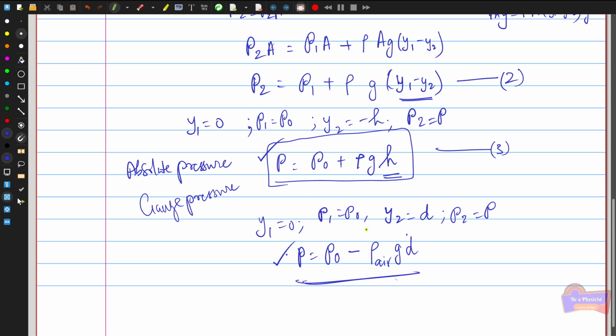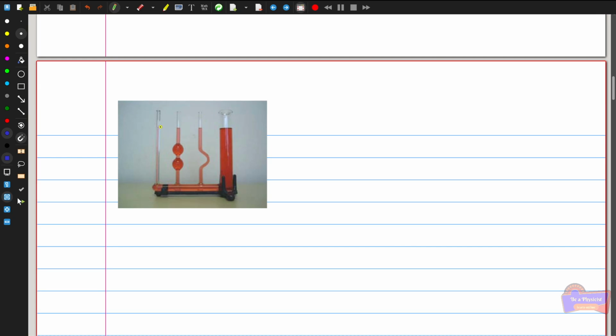from the surface, and not on the shape of the container. So if you take any container and pour the fluid into it, the fluid can freely move into the various parts. If you consider a container like this, with different shapes, and pour water into it, the fluid will freely move into the various parts and stay at the same level of height in every part of this container, regardless of the shape of the container.